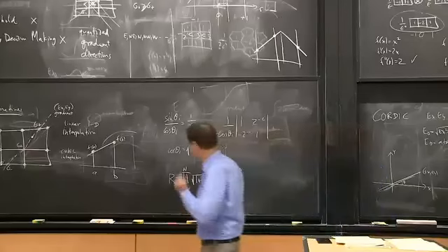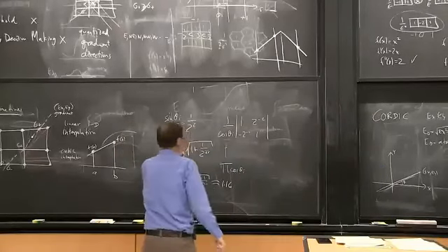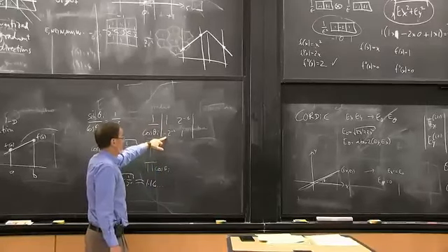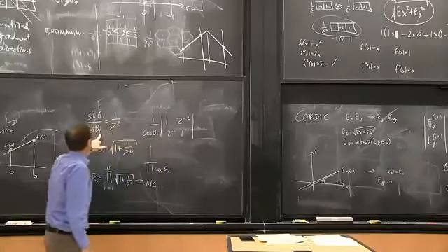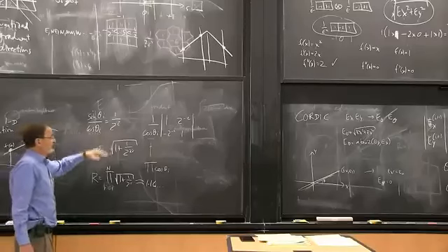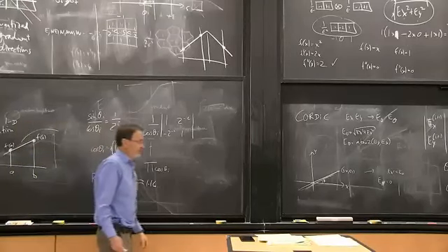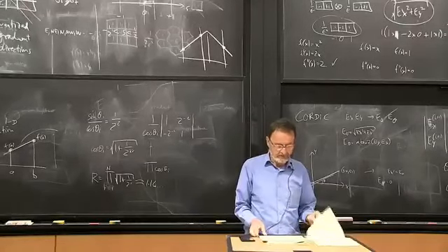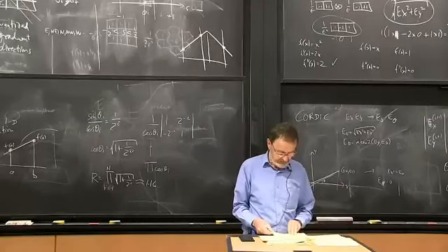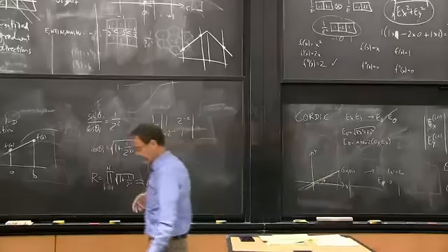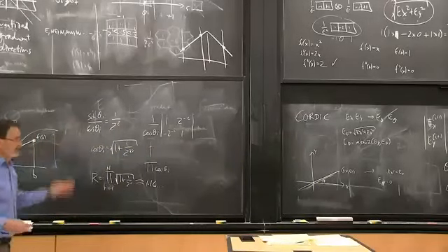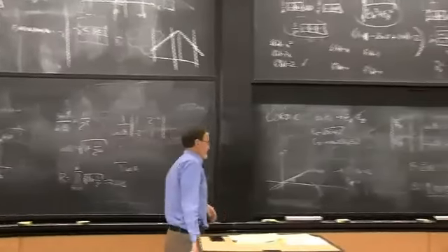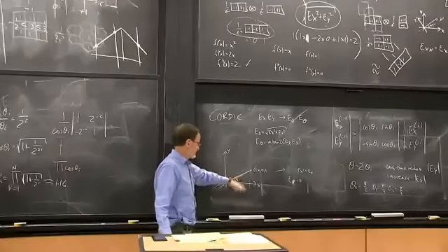Okay, so that's the basic idea of CORDIC, that we rotate, but through special angles that have this property, where the tangent of theta i is 1 over 2 to the i. Well, it takes a bit longer to explain it in the paper, but that's the basic idea. And so the iterative process is you change through that angle, and if it improves the answer, you keep it, and then you keep track of whether it got negative or not.